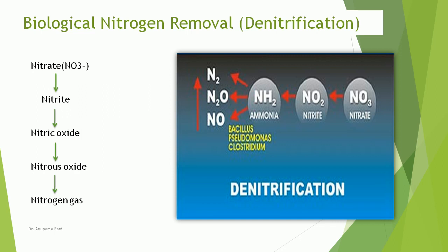For reduction to occur, the DO level must be near zero, and a carbon supply must be available to the bacteria. Because a low carbon content is required for the previous nitrification step, carbon must be added before denitrification can proceed.